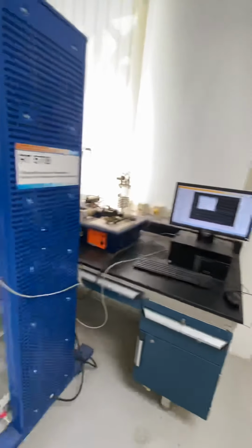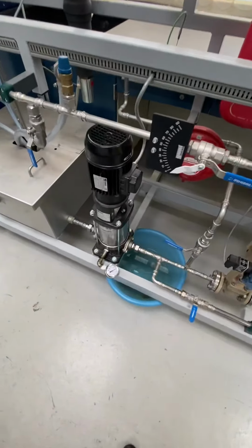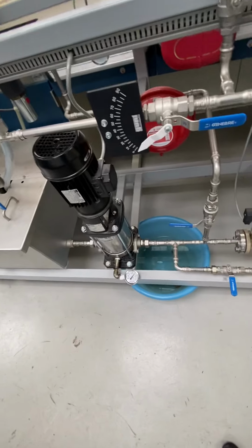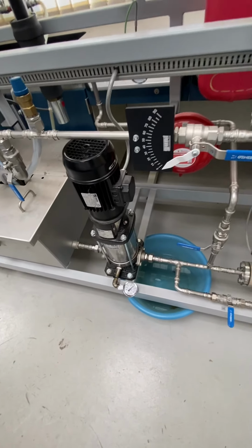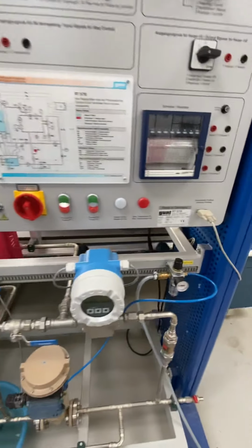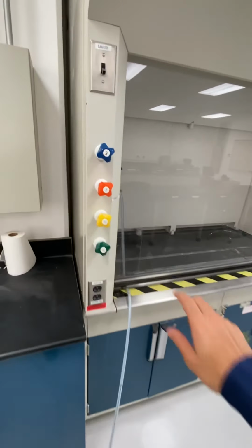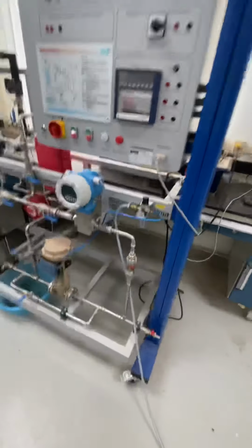Now I will have to do this real quick, and I don't really have to worry that much about the pump, because the discharge pressure is actually very low. It's not at maximum speed. So what's going to happen here, guys, is that I will close the air supply valve, and then I will vent the air.